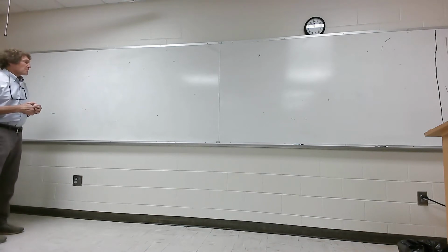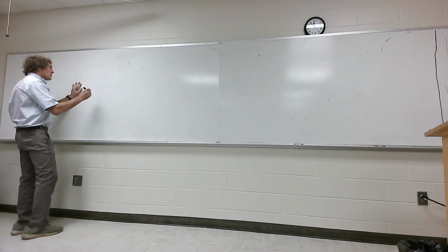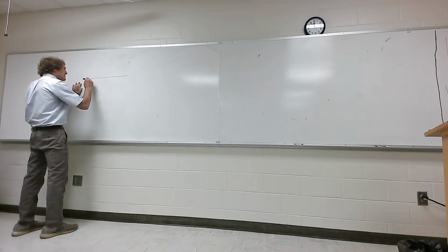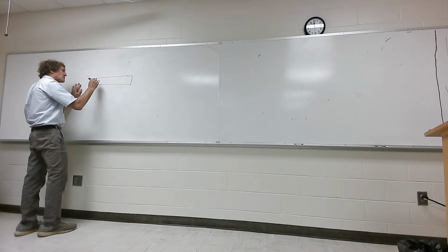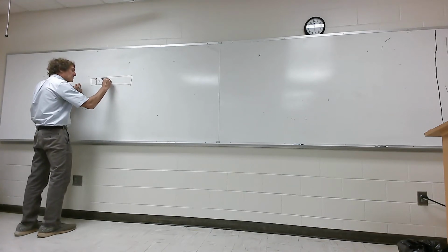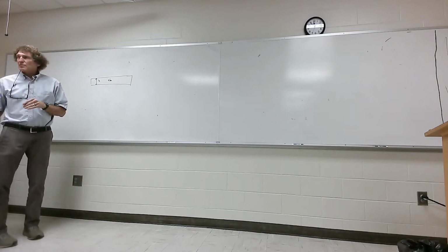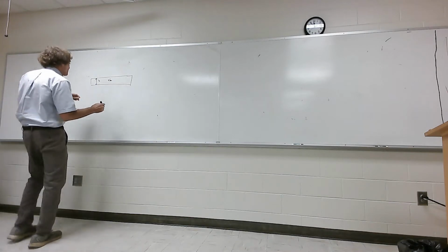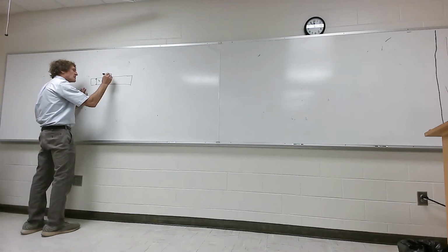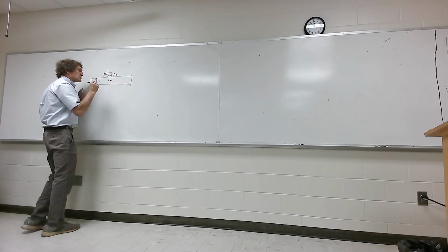But first of all, with microwave engineering, what you're really talking about is a board that has a given height. It has some epsilon relative, permittivity, usually somewhere between 2 and 4, maybe 5, but it's not real high. And then on top of this board, you're going to have things that have a line width. This is made of copper, and you're going to have a certain thickness to it.